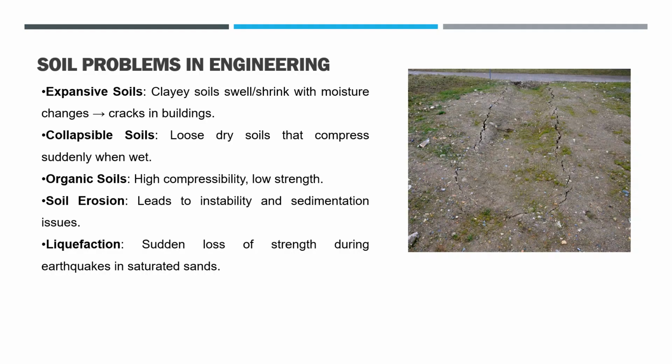If the soil has liquefaction effect, sudden loss of strength during earthquakes takes place in the saturated zones. So all these stated problems may lead to the complete disintegration or collapse of the structure. Hence, proper knowledge about the properties and behavior of the soil is required.